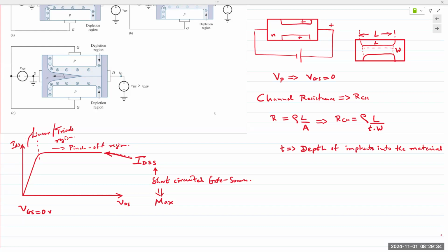Well, Zener, yes. Zener would limit the voltage, yes. But Zener will also have its own current limit, so power dissipation maximum for the Zener. JFETs will also have their own limits. So it's not as if it's always going to survive.